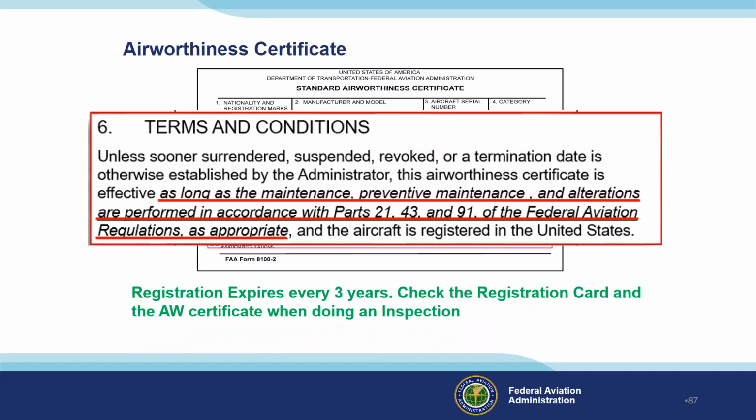Registration expires every 3 years, so make sure you check the registration card and the airworthiness certificate when you're doing an inspection.